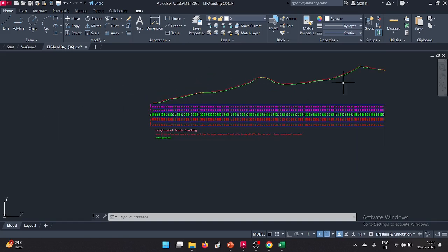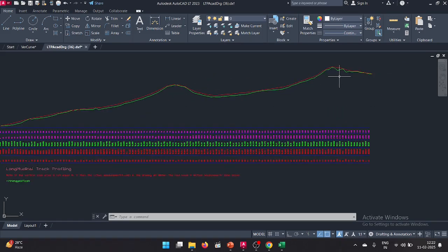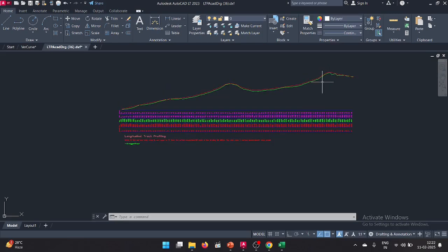Okay. Normally, in railways, whenever we do correction during the maintenance, the undulations will always be there afterwards, because even though we are perfectly packing on time, it will not last long, and in the course of service it will run down because of ballast attrition, train traffic, and also weathering effect. Always the track will run down.